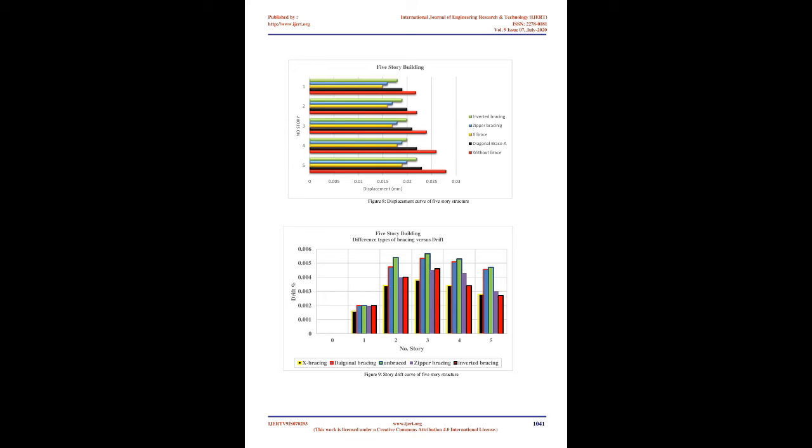Steel bracing members decrease the shear force, reducing the bending moment on the columns and the beams in the structure. Also, they decrease the lateral displacement of the building. The earthquake loads are shifted as an axial load in the steel bracing members. It's possible to use different kinds of eccentrically braced frame like K-shaped in the global bracing along the building height. Sometimes it's possible to use concentrically steel bracing systems like X, V, Z, diagonal bracing inside the vertical members of the structure.